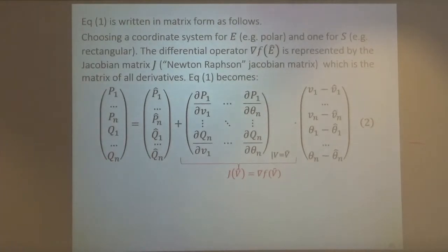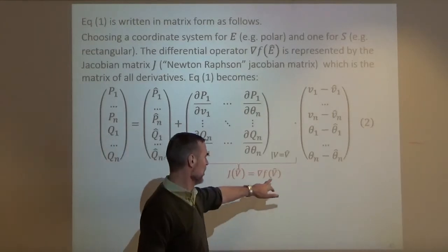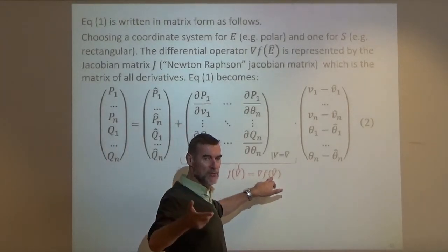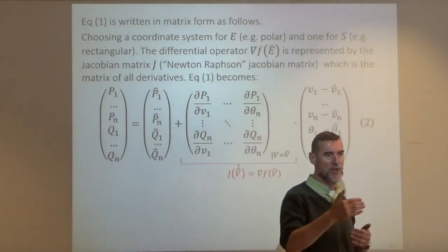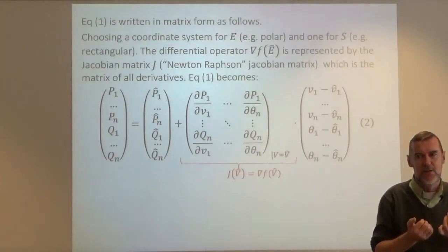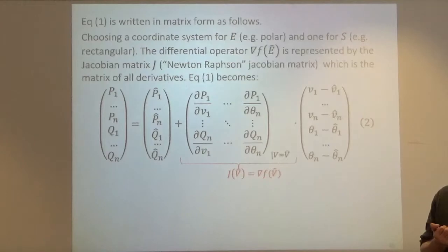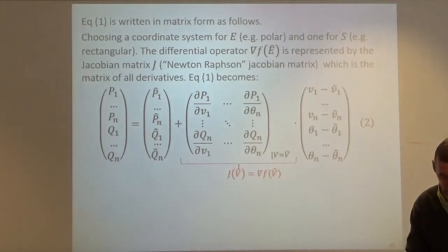We measure all the power injections, and we want to curtail some PVs, for example, because there is a voltage problem due to high PVs. So we want to do a small delta from an operating point. So this would be the operating point where we are, and we want to compute the optimal PV curtailment. Optimal here means we want to curtail as little as possible to bring the voltage back into the nominal values.